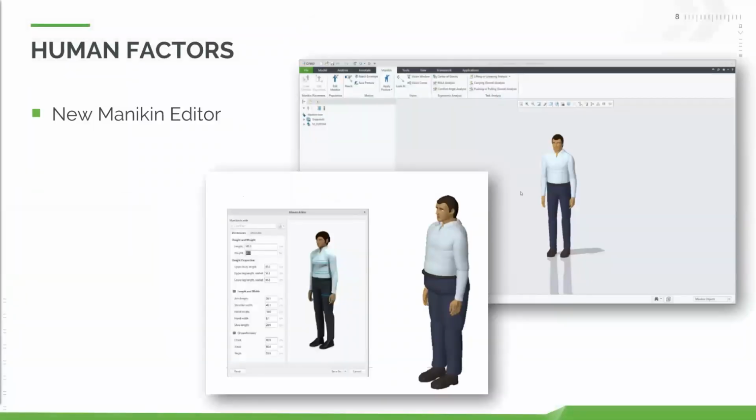One big thing, and we're going to go ahead and show what this looks like in Creo, but we have a new mannequin editor. There's a new custom mannequin that you can take, change, resize, whatever specific design needs that you have. And once you do that, you can then save them off. You can save as many different mannequins of your own size and shape. And after that, go ahead and use them inside of your assembly, just as you would with any other mannequin. So really nice addition there.